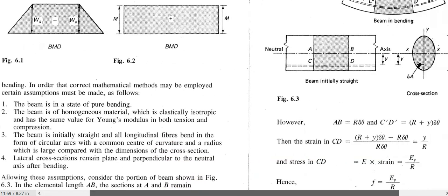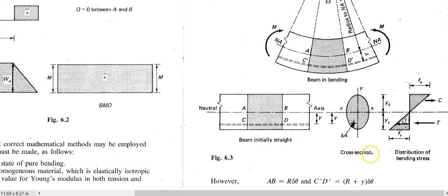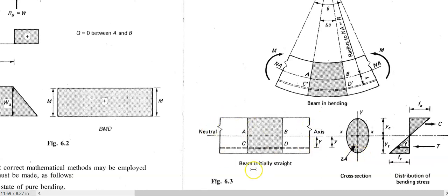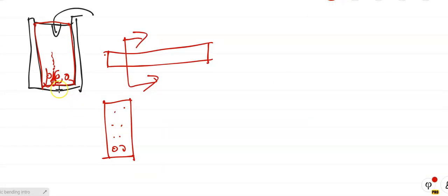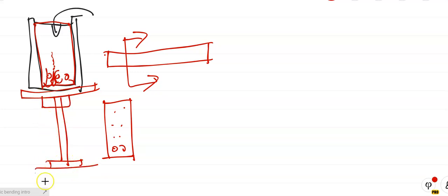Wow, that's a mouthful. Let's go over to the sketch on the page there. What it means is that there's your beam. The beam is placed in the form. The forms are supported. We have props under here. Props look like this. There's a prop there, it sits under there like so. Okay, so there's the ground. It's jacked up, it's adjusted. So this prop and this bearer here, and that bearer there, is holding up the formwork, which is the molding.